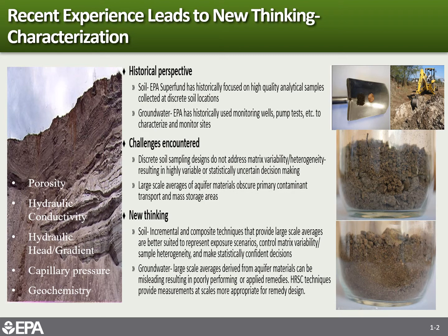And those are better suited to represent our exposure scenarios, oftentimes in things like surface soil exposure scenarios, and help us make statistically confident decisions. And in groundwater, we're finding that if we can move away from the large-scale averages and use high-resolution site characterization techniques, when we get measurements that are more scale appropriate, we can tailor our groundwater remediation to help us address those challenges.